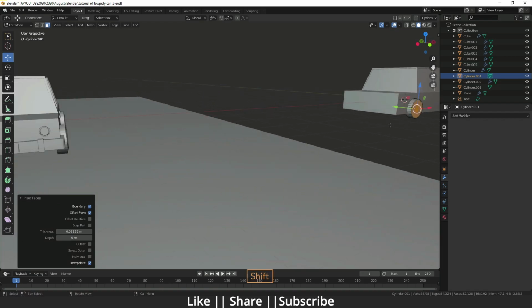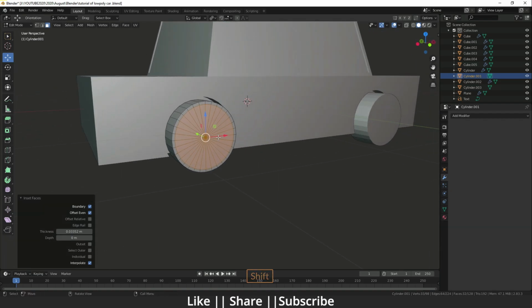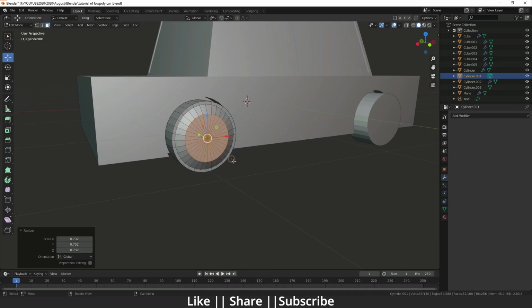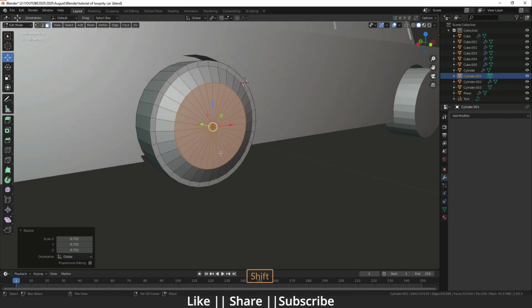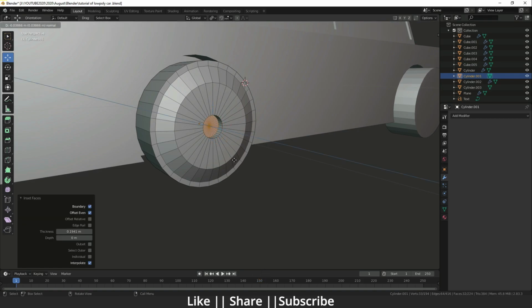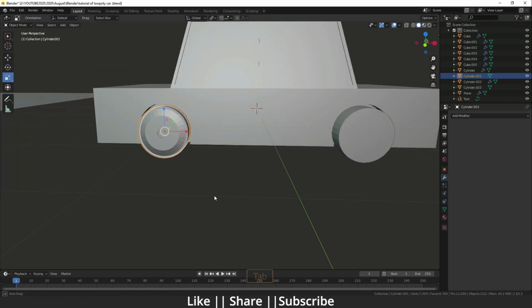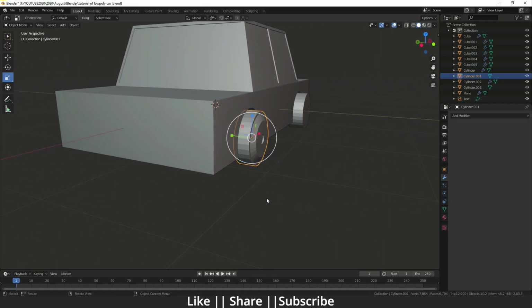Okay, so for that we have to do insert a little bit like that. Then after that I'm just going to extrude like that, and then I will do scale. So here you can see. Okay, and then I will do insert again like that, and now I will have to extrude inside. So here you can see we have a very good low poly tire here.